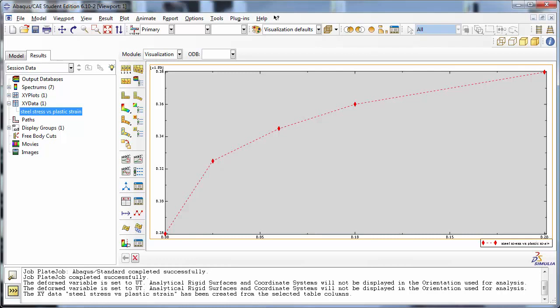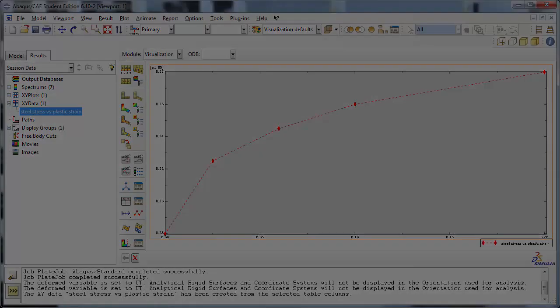In layman's terms, this means it will generate stress-strain data points that will form a nice smooth curve. However, it is possible that the points it generates may not coincide with the original user supplied data points. Abaqus Explicit will attempt to generate a sufficient number of intervals so that the maximum error between the regularized and user supplied data is less than 3%.